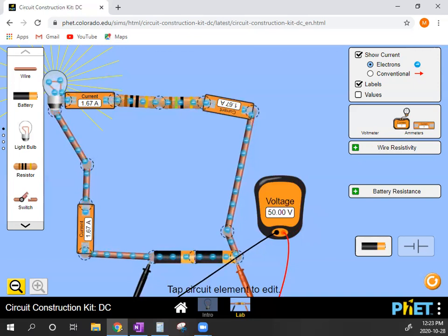But the limitation of the battery is that batteries can only give you so much current. So let's say these batteries, the most current they can give me is at most 2 amps, okay? So if I want 3 or 4 amps, then this won't help me get that, okay? So if my goal is to create a battery system that has a higher voltage, I connect them in series, okay? Now, the other way I can connect batteries is like this.